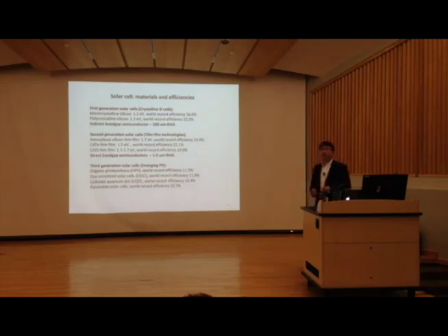For the most efficient solar cell, the band gap should be between 1.1 and 1.5 eV. Below that, even if you harvest more infrared energy, the voltage you produce is lower, so in the end the total efficiency will be lowered. That's why silicon solar cells and other technologies always stay within that energy range, between 1.1 and 1.5.